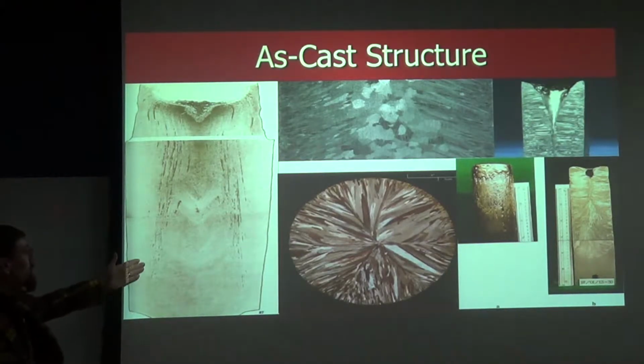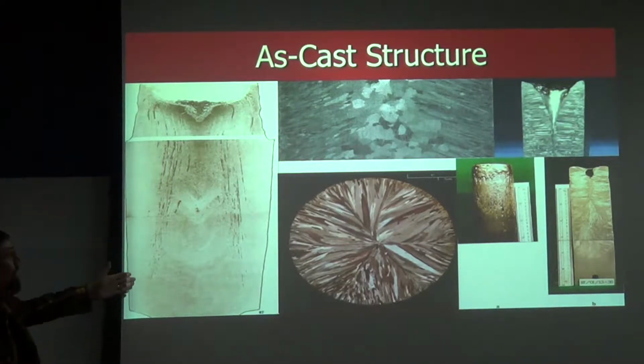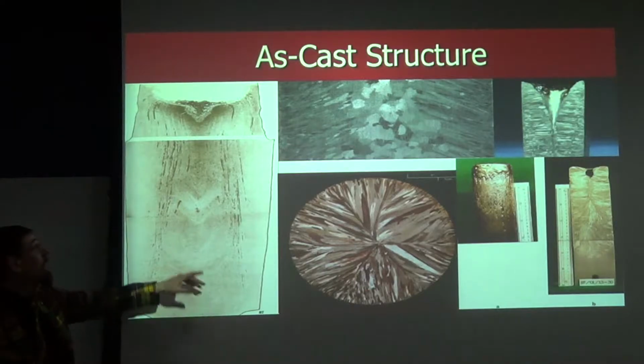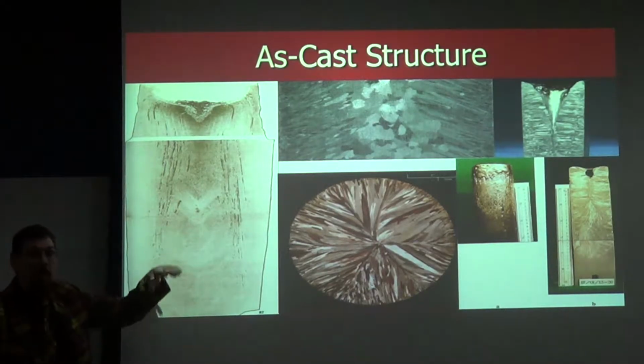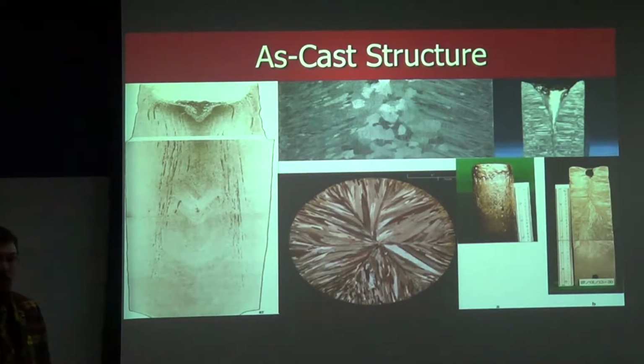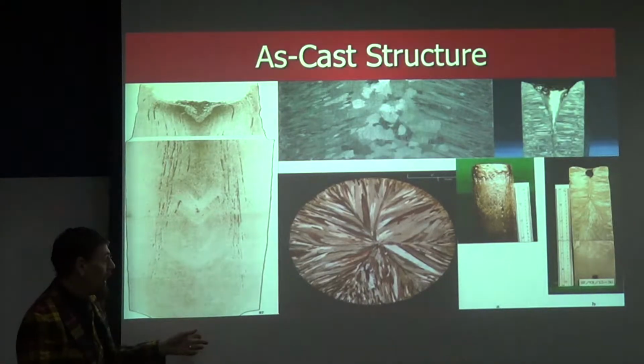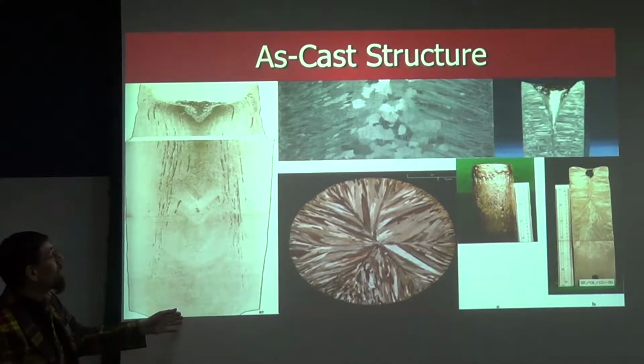Here's a cross-section of a larger ingot. This is more of what we would expect to see in the world of steel forgings. We have some distinct regions. Not shown right here is the very bottom of the ingot. The opposite is the top. Ingots in the steel world are cast vertically. And not only are they cast vertically, but they're cast in such a way that the metal flows in at the bottom. Again, we'll cover that in more detail in a little bit.